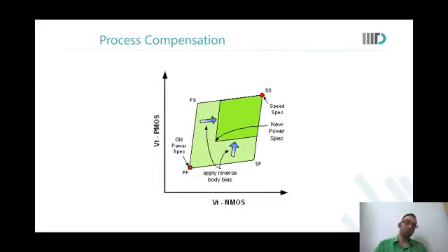Yes. So very, very good, Raghav. I'm so happy that you're able to anticipate the problems that can come with body bias. So in terms of forward body bias, you have to realize that you cannot really forward body bias your PN junctions beyond 0.2 or 0.3 volts, because otherwise the leakage currents would kind of run off.